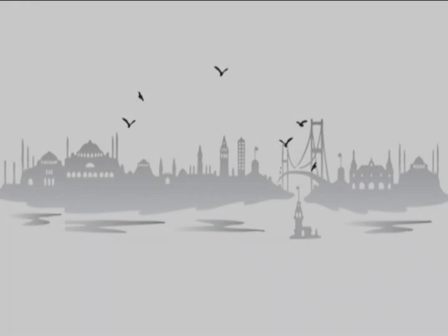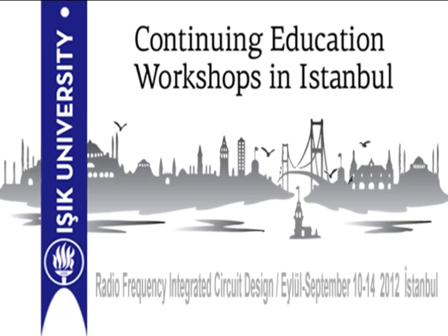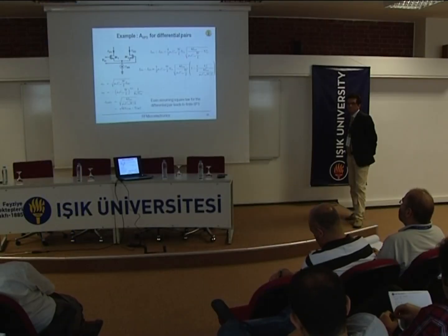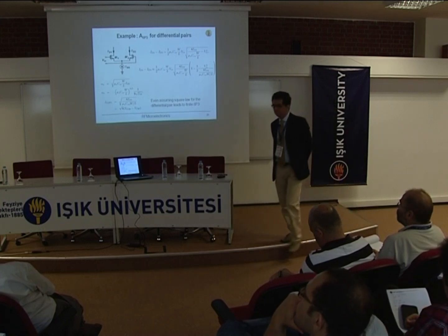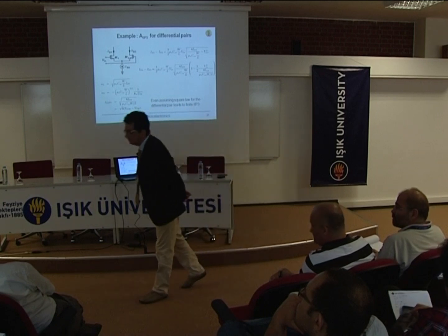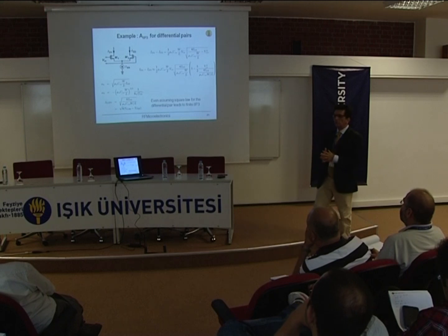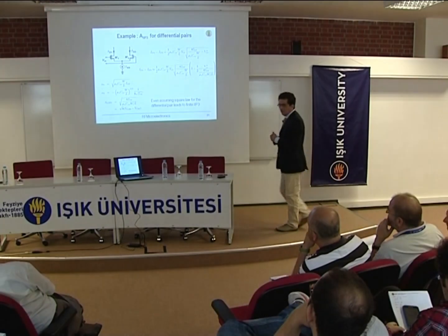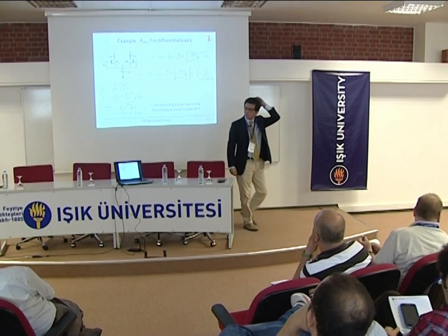Final ID1 minus ID2 versus V in has a third order coefficient and is responsible for third order intermodulation. So is there some intuition about it? So the recommendation is to have larger overdrive, yes. Larger VOV, yes, that's in general. But my question is more philosophical. I'm saying if it's just square law, why are we producing third order?